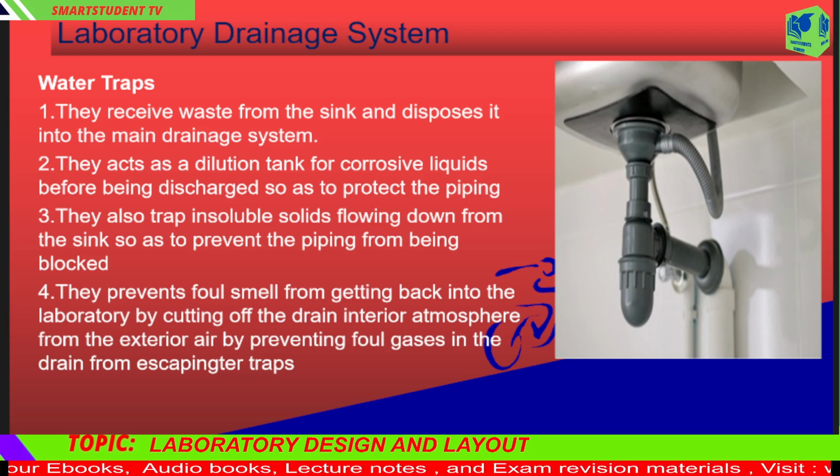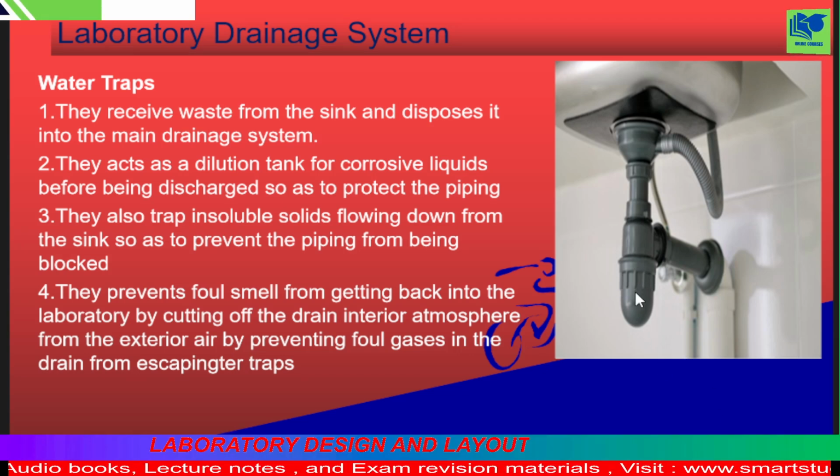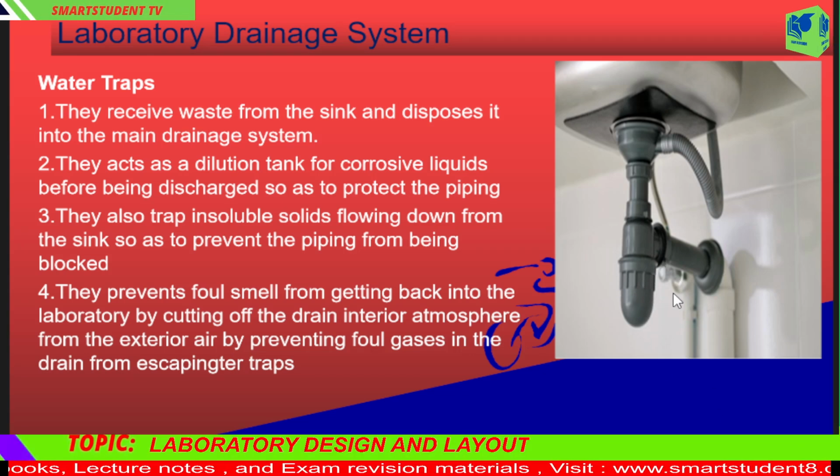The effectiveness of a trap is dependent on the depth of the seal, since the deeper it is, the more it will resist the pressure inside the drain. All traps must be able to meet the following requirements to be effective.